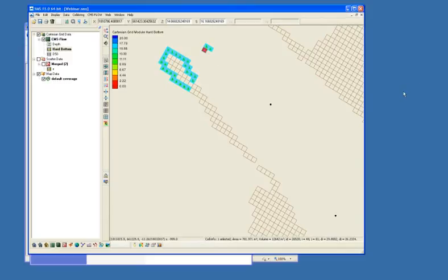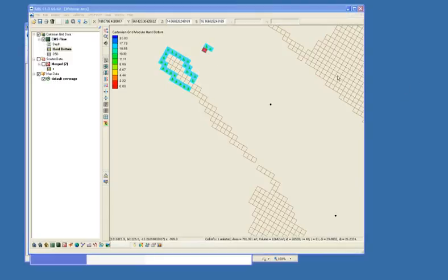I see there's a couple of questions I'll try to answer real quick. Can you set an erodibility coefficient for the hard bottom? No coefficient is available right now. The way that you could do that is, if you're using multiple sediment grain sizes, you could specify values in certain areas with a larger grain size so that it's harder to move.